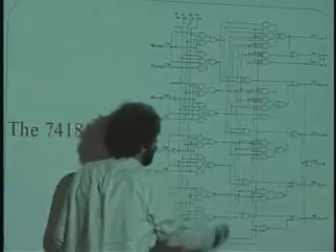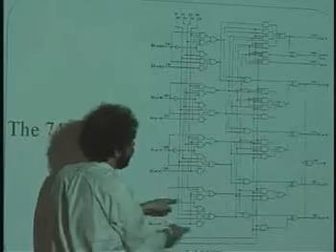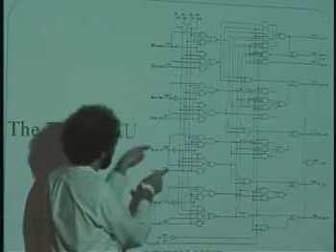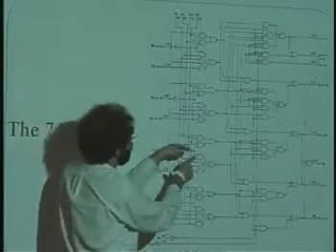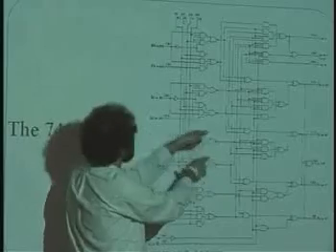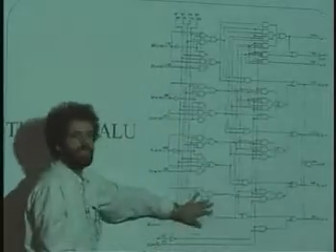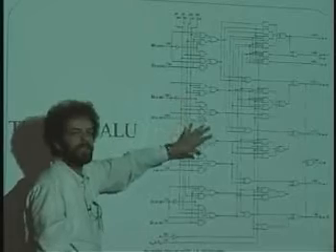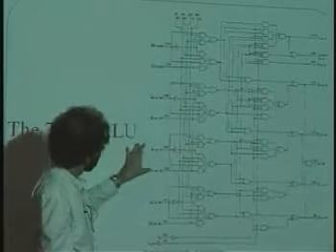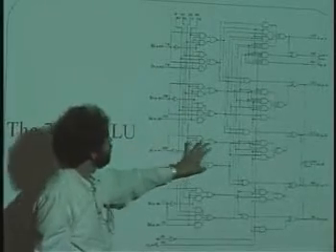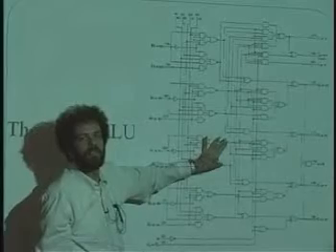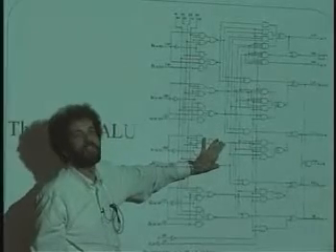There's a line right here where every bit of A and B is recoded to create 2 outputs, where bit 2 of A and B is recoded identically to each stage. Every stage is the same. Guess what the recoding is here between A sub 1, B sub 1, and the mystery wires right here. The mystery wires are G and P.